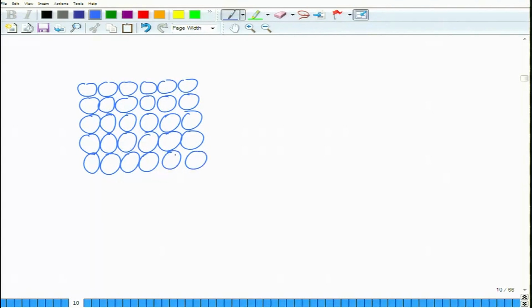Now, what we do here is we remove some of the atoms. So, we remove these two atoms, let us say. What happens in this case now, this structure will slightly distort, because you have created an extra row of atoms in between which does not completely go through the material.